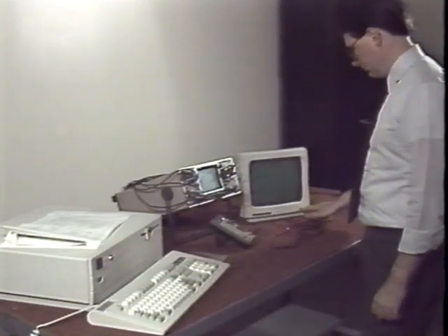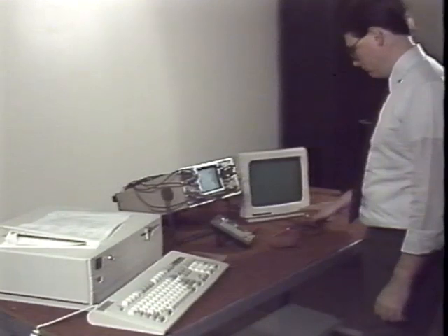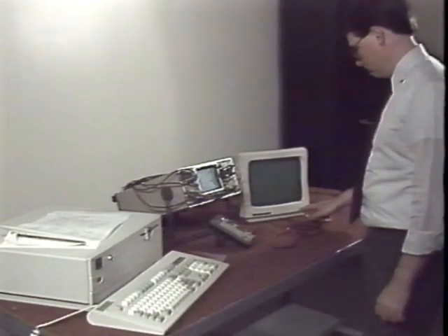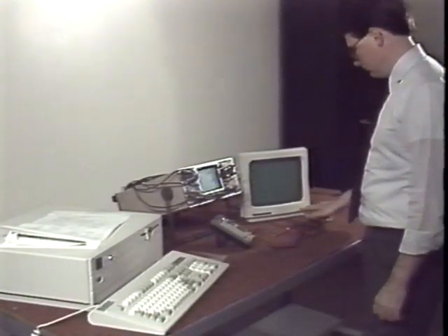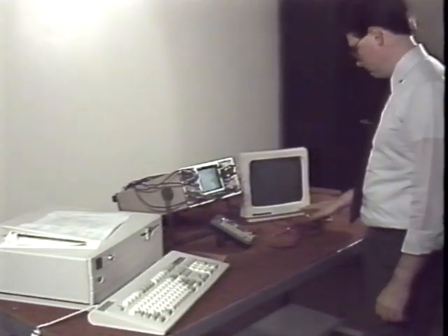Before leaving the sweep adjustments, turn the monitor on and off several times and make sure that the display always powers up stable. It is possible to set the horizontal or vertical oscillator right at the edge of its capture range so that it sometimes locks to sync input but other times does not. If this happens, readjust the sweep sections until you get a stable picture at all times. This will prevent intermittent heat or stress-related sync problems.